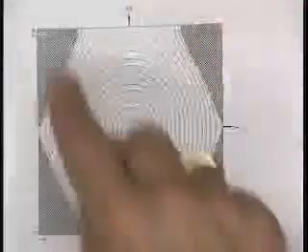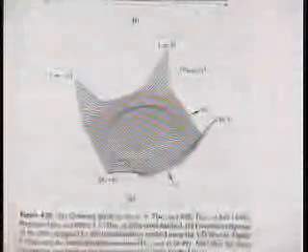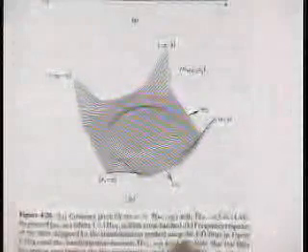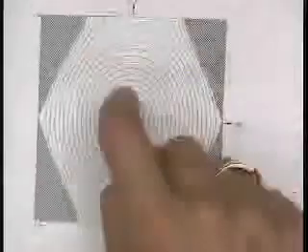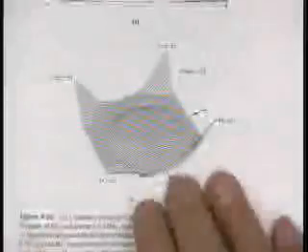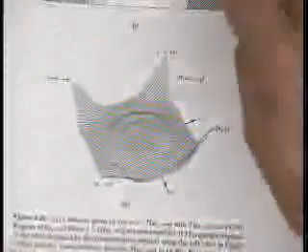It exceeded 1. And if you plot it here, you can see that in part B, what you have is the frequency response of the filter designed using this. If you don't do anything more, this is the frequency response that you end up getting. In these four corners, things are all messed up, and believe me, these four corners are high frequencies: pi, pi; minus pi, pi; minus pi, minus pi; pi, minus pi.